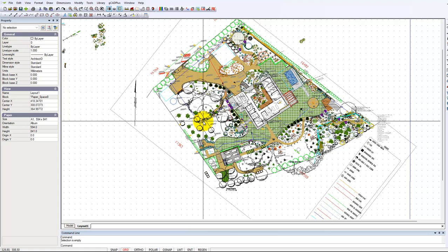Sorry, I recommended initially getting details in the model space out, and that should improve stability of the drawing. Now I suspect the major difficulty here was the very large number of blocks that were inserted into layout space. I'm sorry that's been so long and so waffly, but I hope that's of some value.